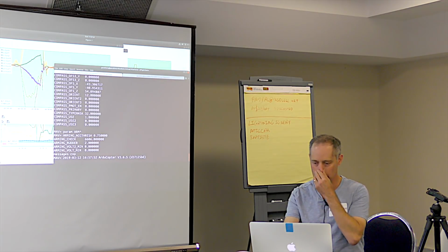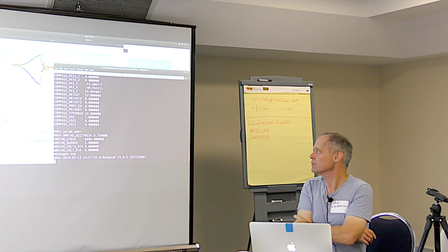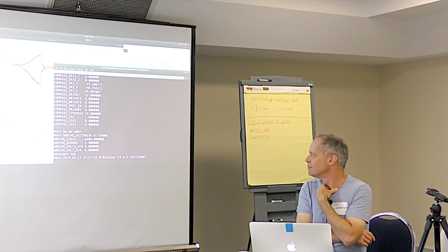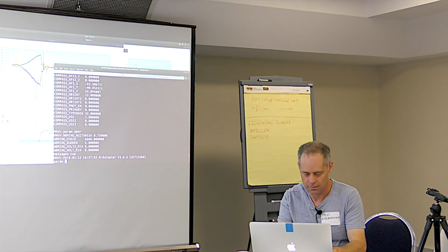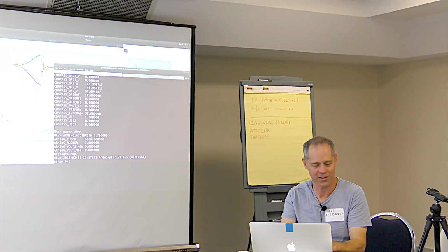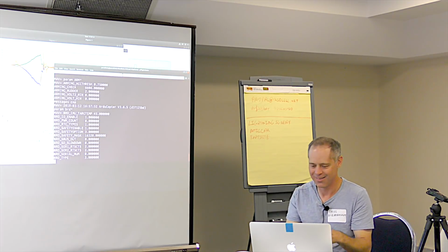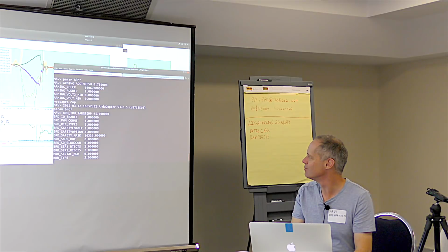Okay, we see that it's ArduCopter 3.6.5. And param BRD_TYPE, board type. See what type of board it is. Looks like a cube. No, that's not a cube. BOARD star. And board type is 3, so it's identifying as a cube type.